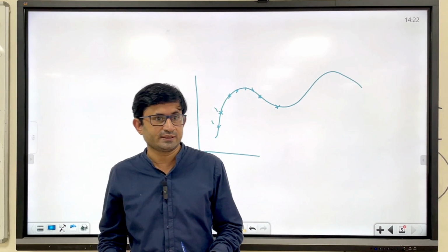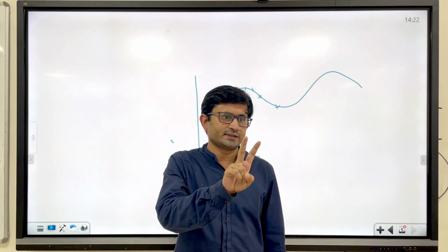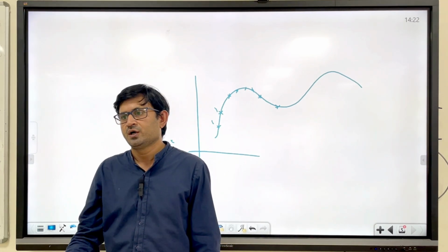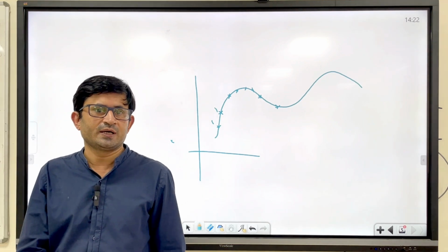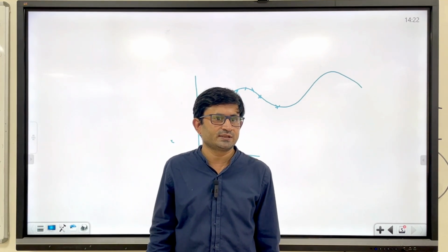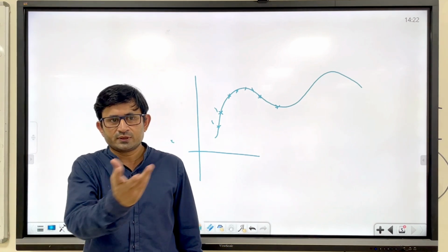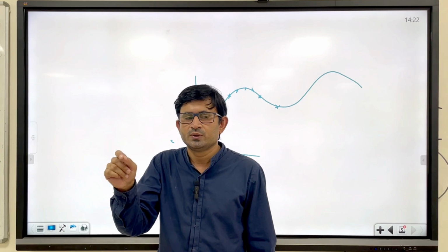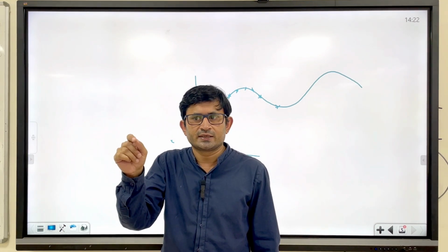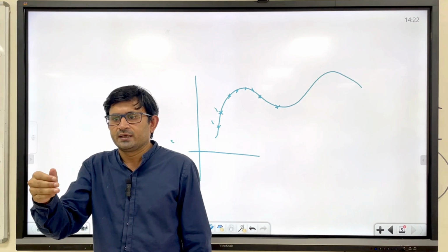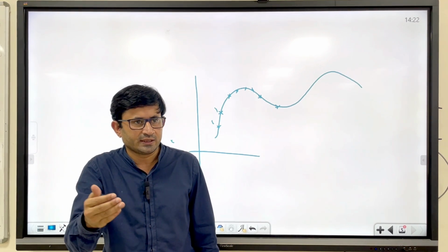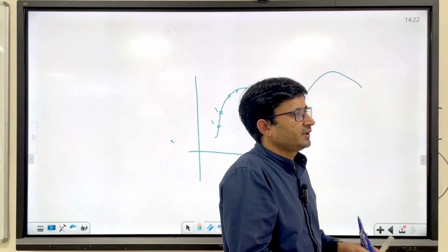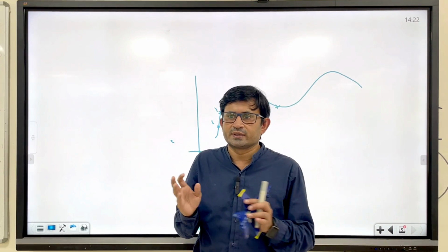Okay, so I said that you can use two techniques, either small perturbation theory or Taylor series. In small perturbation theory, for example, if your aircraft is flying at some particular trim condition, U0, V0, W0, you add the disturbances delta U, delta V, delta W in all the states, and similarly delta P, delta Q, delta R, and you put in the equations of motion and rearrange the things, you will get the linearized model.